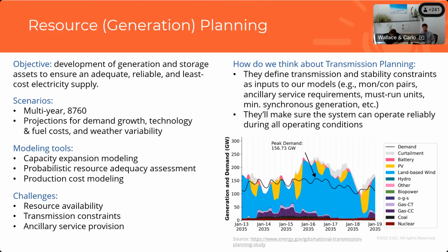I want to consider ancillary service requirements, primarily in terms of frequency regulation, so regulation reserves, load following reserves, and other type of inertia and frequency regulation reserves, but also potentially other ancillary services requirements that the transmission planner may be able to provide, such as voltage regulation reserve.